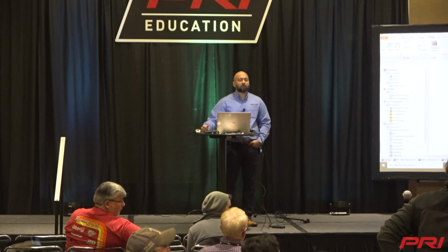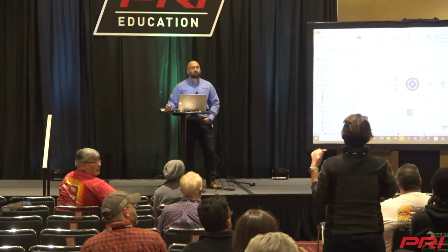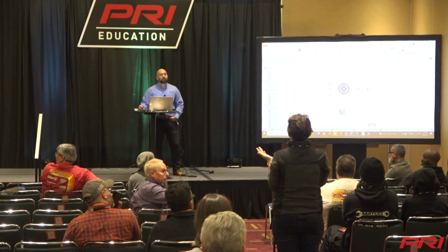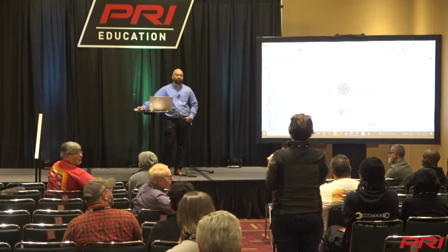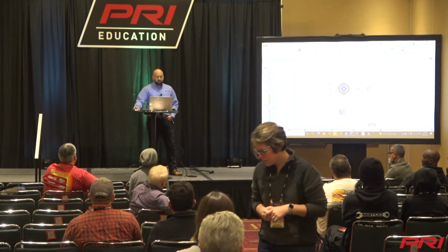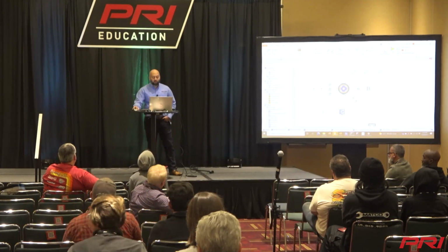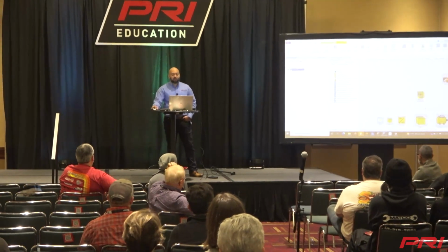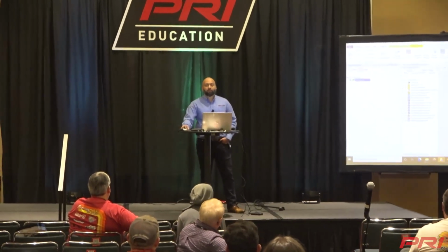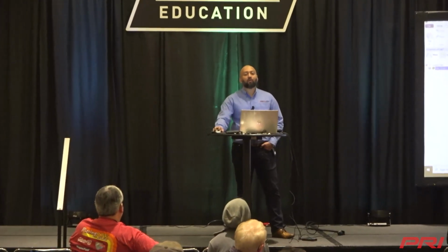So a question on the driver profiles. How would you model or translate this to a track? So is it spatial, or how do you get that profile? Yes, there are different ways that you can model that. Right now I showed a case where the driver is following a speed profile. But you can also have the driver follow a distance profile, and then whatever time it completes that profile in helps you compare between, let's say, two motor types. You can do that as well.